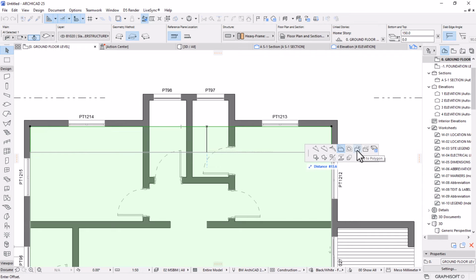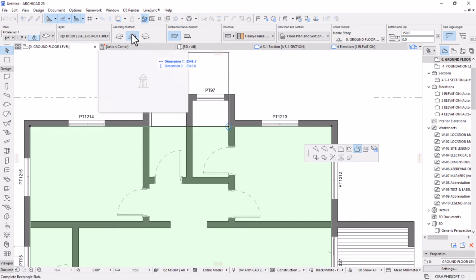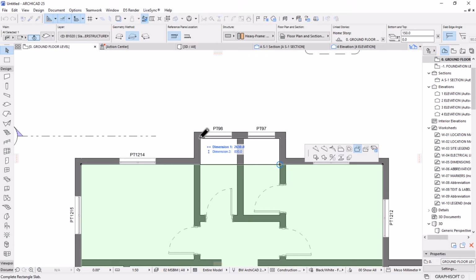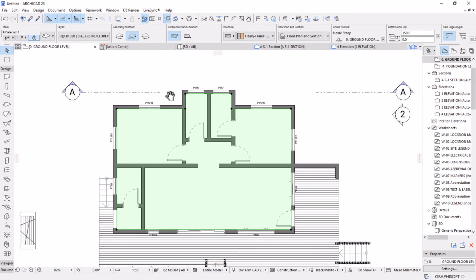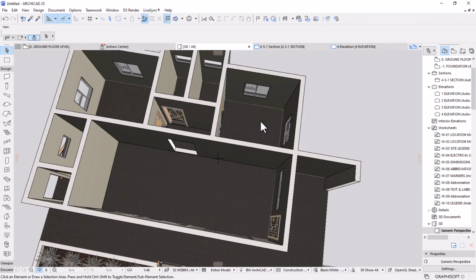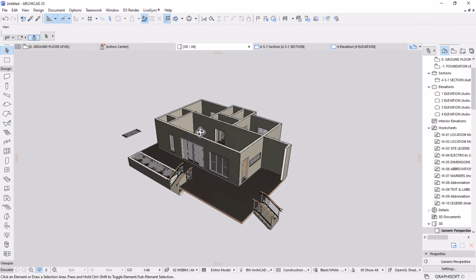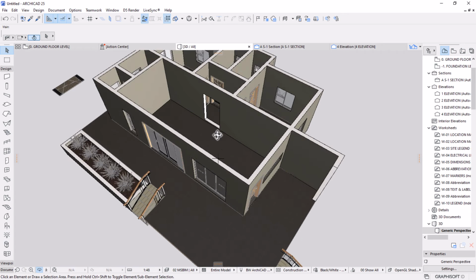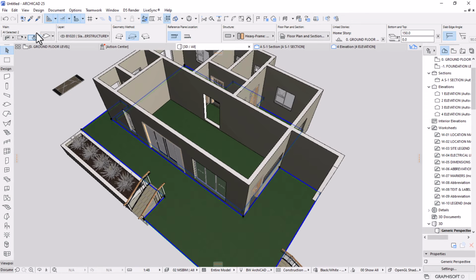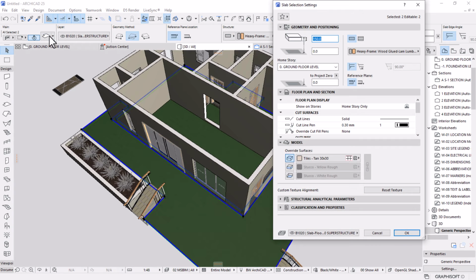Then I'm gonna activate the add to polygon tool, and then I'll pick this point, draw a rectangle, make sure the geometry method here is on rectangle, and draw to place that. Perfect. So now we have our what you call this place, and then I'm going to select all these slabs and then open its settings.